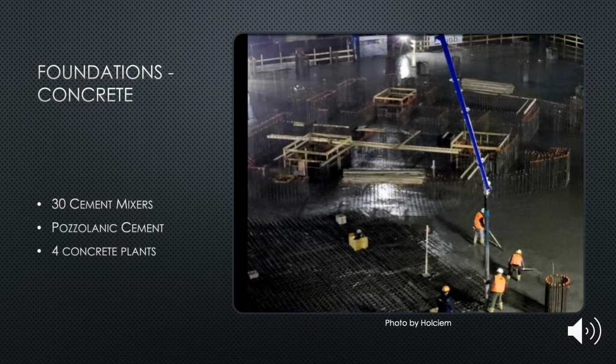The base of the foundation was poured using cement with a low heat of hydration, specifically designed to reduce the risk of cracking. The mix involved the use of a 32.5R IVA pozzolanic cement. Pozzolanic properties basically allow the control of the heat of hydration, which is what causes the cracks. The cement was then covered in mats after it was cast to prevent any moisture loss and again to prevent cracking.